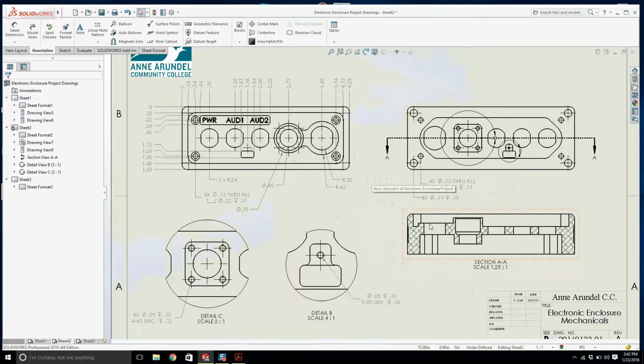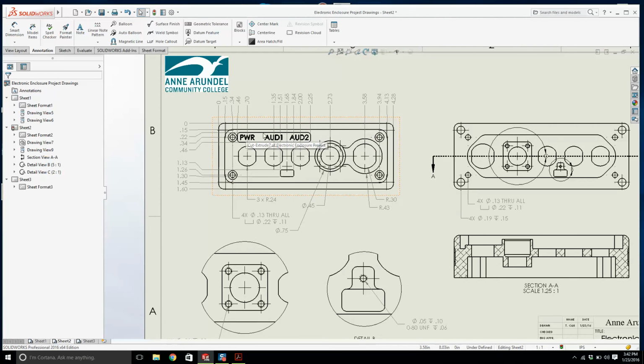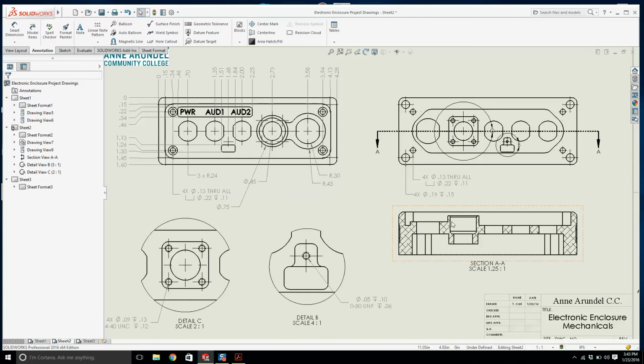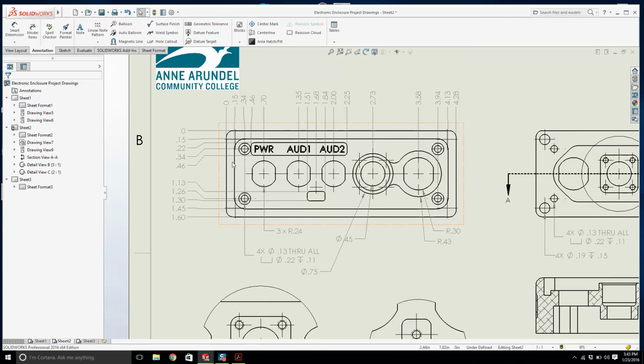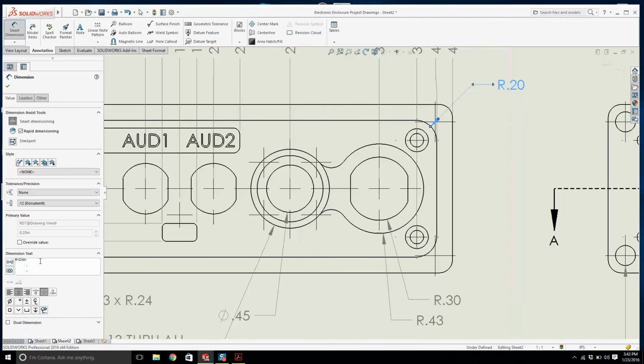Another piece of advice: whenever you're creating drawings, and I'm definitely not doing this now, what you do is imagine if you had to machine this part yourself. This is why the best drafters and mechanical engineers are people that have machining experience. I'll give you a small example. I know I need to start off with a block. So the block is 4.28 by 1.6, and then I have its thickness. That's the first thing I'm going to do. The second thing is I'm going to cut out this area. Now I can see that I'm missing a radius. So I'll add the radius in. Let's put in ×4.